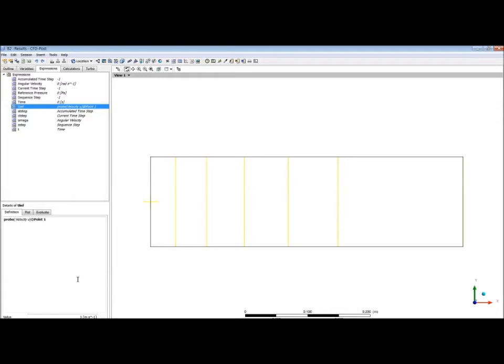We could have set it higher, we could have changed it. So what we're going to do next is create another expression called unormalized. So new, unormalized there, like so. And for this one, this should be velocity, and this uses the entire velocity variable divided by U inf, the value of the expression we created there, and it should say it's created a variable there called unormalized.